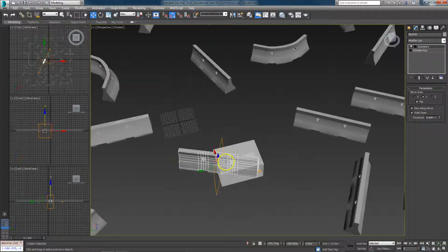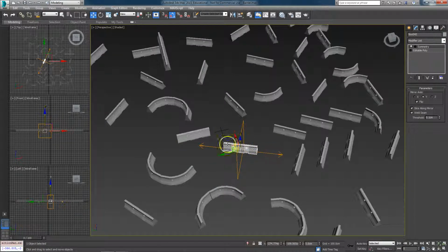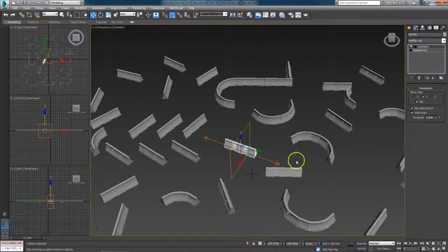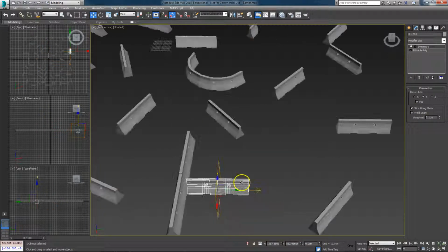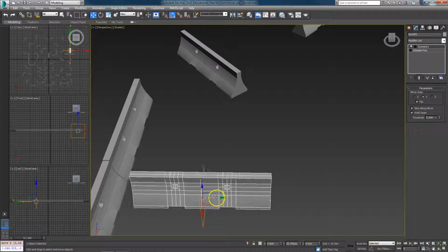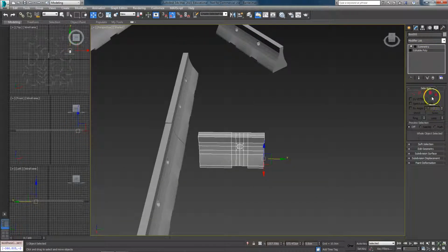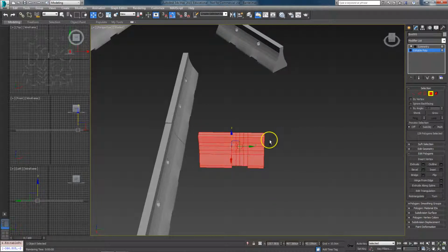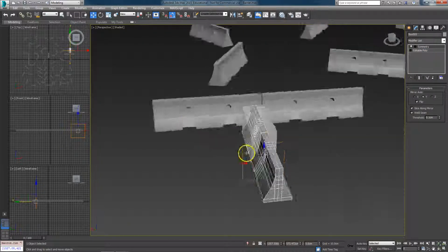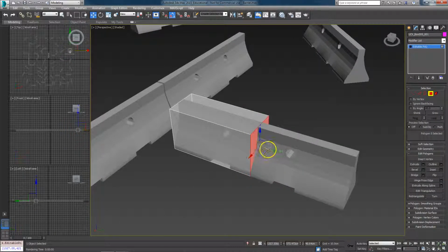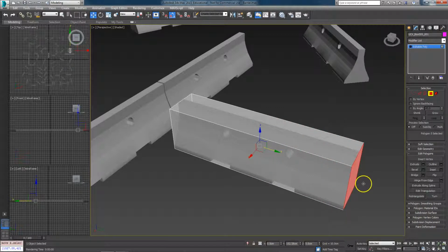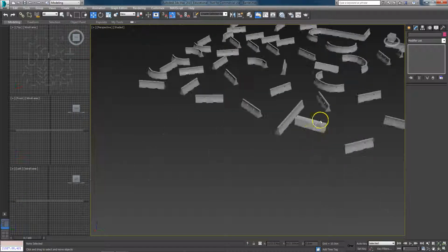And then you can see here, based off of the angle, because it's going to create the UVs based off of the local axis. Because this has been rotated, we end up with that type of issue. So let me find one that's straight based off the original. Actually, it doesn't look like it. This one does look like it. So we'll use this one. Drop down, select the faces, run the script. There we go. And then all I'm going to do is just select that one and then pull it out so it fits the whole thing, like so. Alright, so if I remember where that's at.